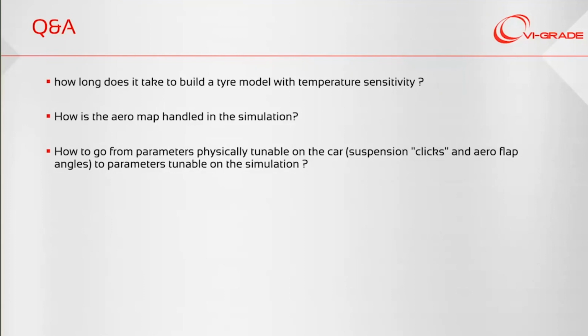The same can be said for the aerodynamics. If you need to study a specific flap angle, you will need to provide either a dedicated aero map or take advantage of the modifiers on the aero maps, which, as I said, either scale or offset the map output into the simulation.